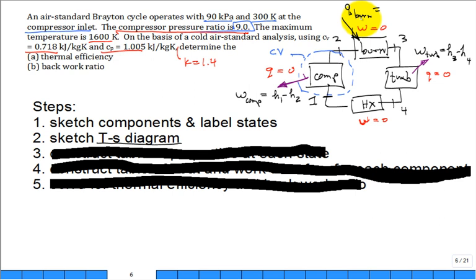Do the first law. It's going to be related to a change in the enthalpy. It'll be H3 minus H2, right? And here again, it's a little convoluted, but I'm going to show a positive Q in on this heat exchanger, but I know I'm going to calculate a negative Q into that heat exchanger because it's really heat rejection. And it'll be H1 minus H4, first law analysis.